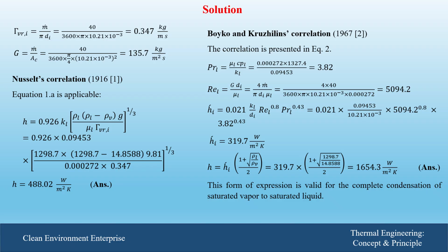Then the heat transfer coefficient corresponds to 1654.3 watt per meter square Kelvin. And this form of expression is valid for complete condensation, where saturated vapor has been converted to saturated liquid at the exit of this tube.